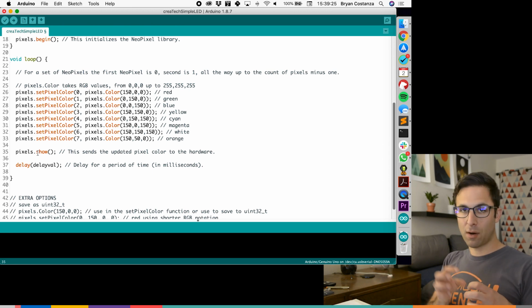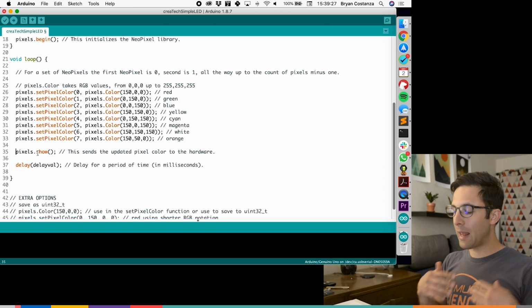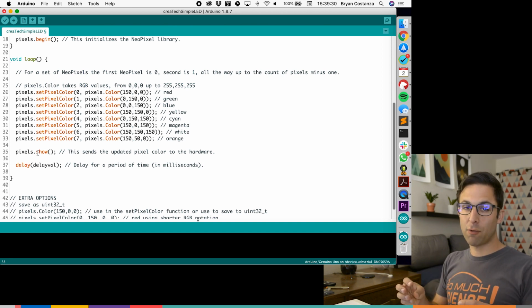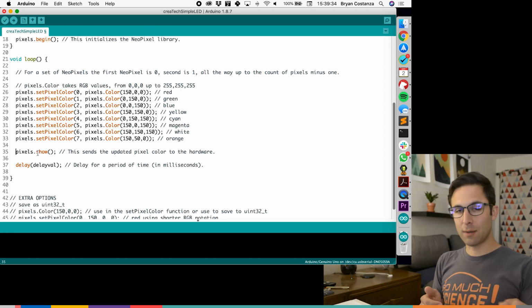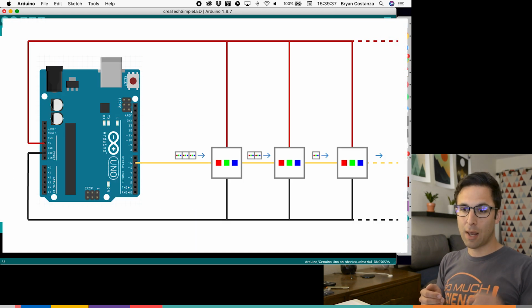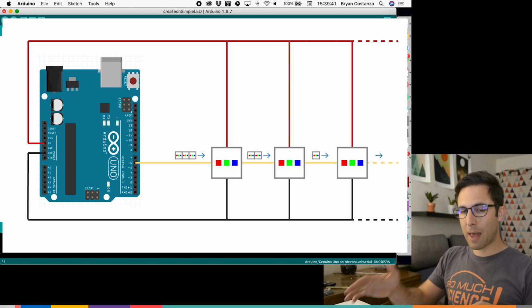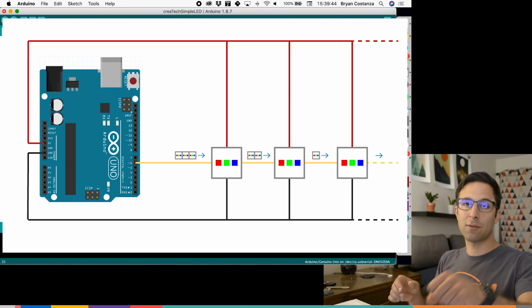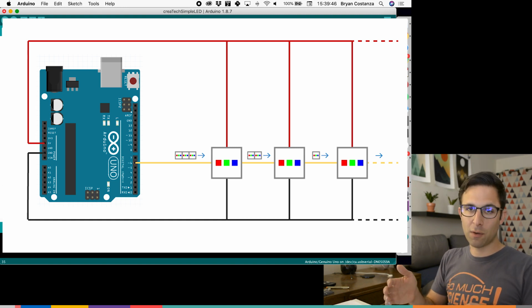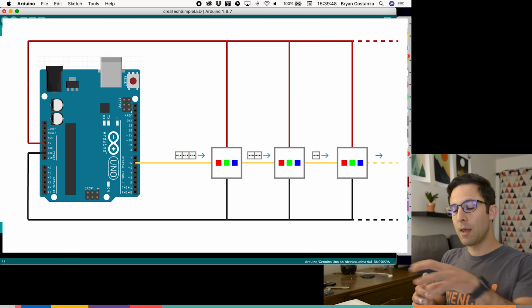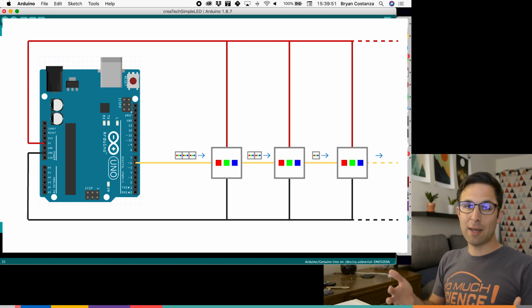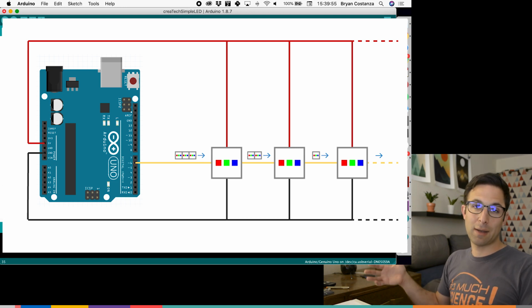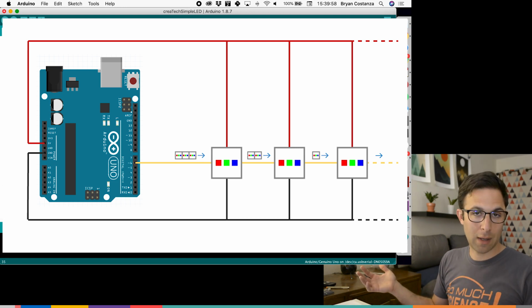So in this case, there are 8 positions, and you will send 8 color values out, and they're sent out in order. The first LED has some circuitry inside of it where it takes the first set of color information and removes it from the packet, but it uses that information to change color, then it passes the rest on. The next LED takes the first that it gets and passes on the rest of the information, and so on. If you send out 8 packets of information and there's 8 LEDs, the last one will take the last packet, and then that's it. And great job.